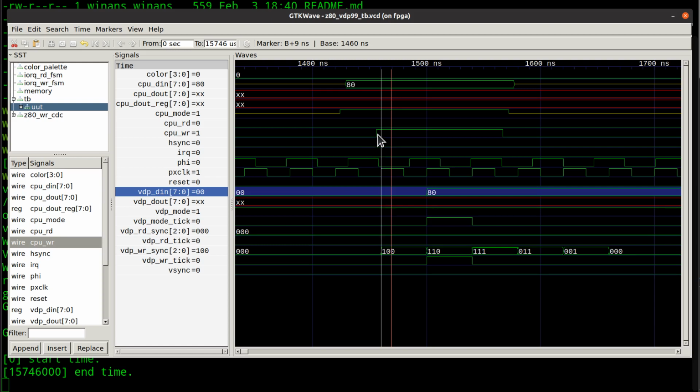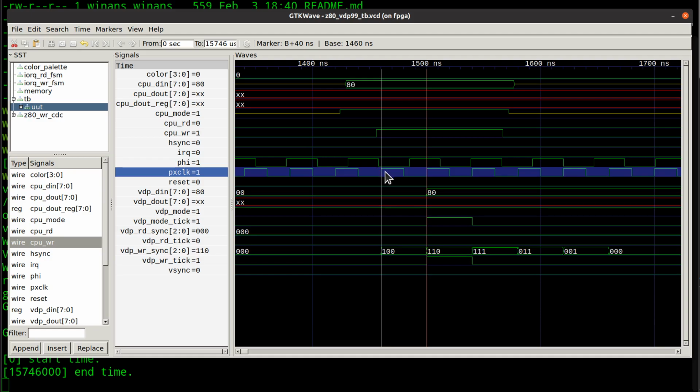But if it doesn't do this and it wobbles around, it might be 100, or it might end up 000. It could quiver a while. And you really don't want to take advantage of the value of that bit until way over here, when it is more likely to have stabilized. Okay? So what I've done is, you've got a whole pixel clock period long to wait for the metastability to settle out.